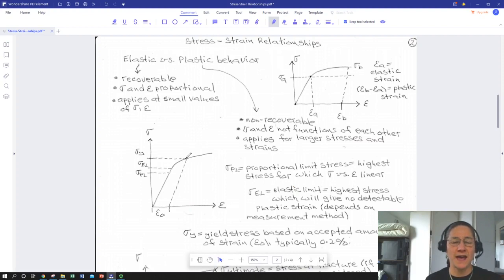You define that as the stress that corresponds to the point here where, if you increase the stress in the material, it yields plastically just a little bit, such that when you release the stress, you let go of it, and you trace back a line parallel to your modulus, which the material will retract along. In this case, if we're pulling on it, you recover all the elastic strain, and you end up with permanent deformation equal to epsilon 0 here.